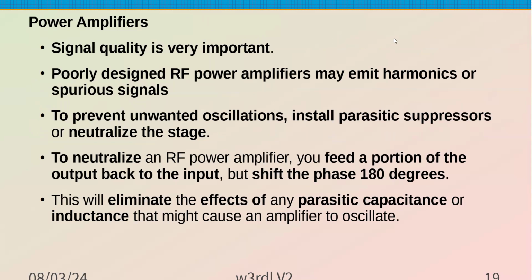With a power amplifier, like a linear, at some point everybody in here will have an external linear amplifier, probably a kilowatt and a half. Depending on how they're designed, they can emit a lot of harmonics. An example is the power amplifier in the cheap UV5 radio, which I think may have improved, but it's got a lot of harmonics.